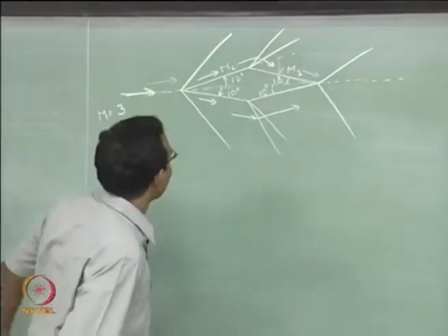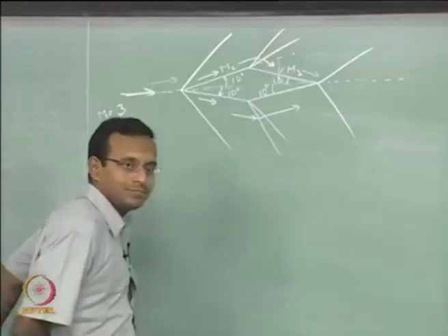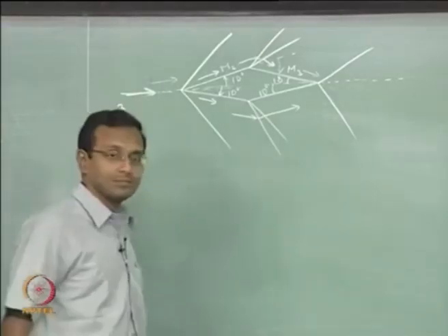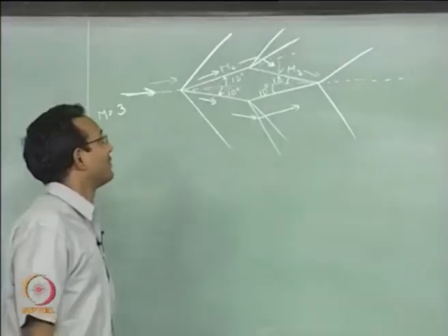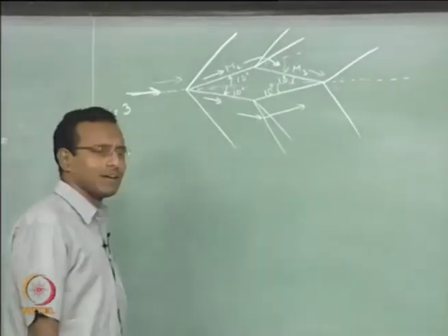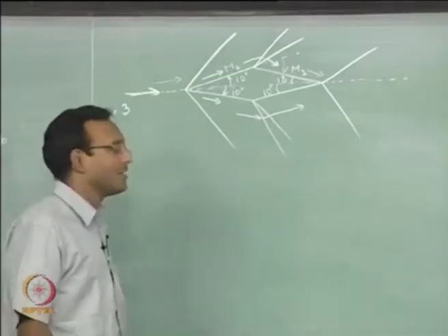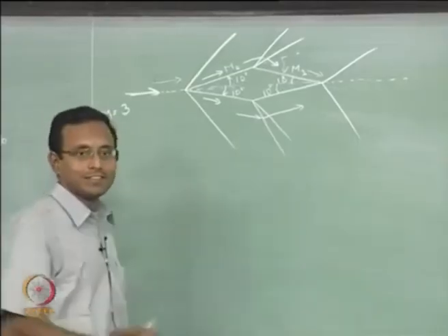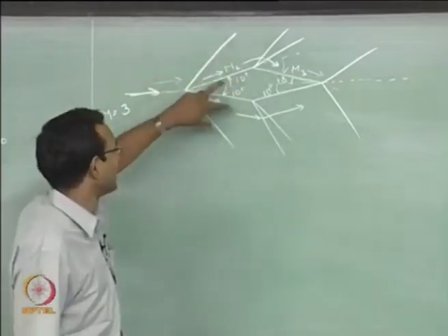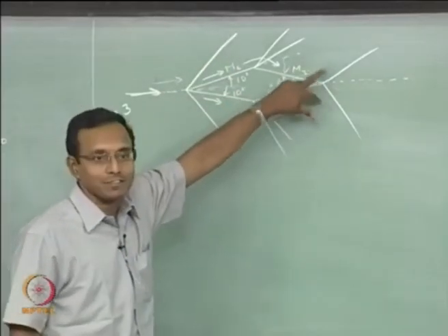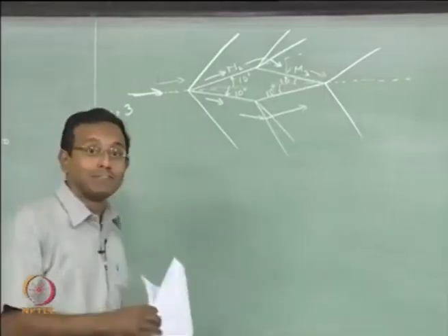Will this airfoil have drag at this angle of attack? Two people say no, one person says yes. So, will it have drag or not? It will have drag. Why? Okay, will it have lift? It will not have lift. Why? It is a very symmetric problem. Okay, whatever pressure is here, same pressure here, same pressure is here and here. So, it is equal, there is no lift produced.